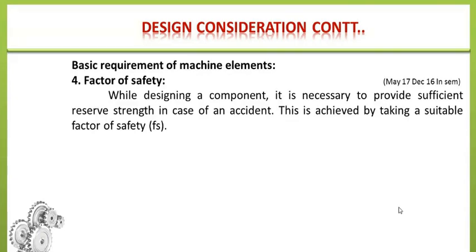So there are two particular points you have to understand. First, the amount of stress generated in the component during working condition, and second, the strength of the material that you select. Now, it is not always possible for the designer to predict all the forces acting on that component. Some forces, because of the very complicated shape of the component, may be neglected by the designer, or because of manufacturing inaccuracy and so on, some forces are neglected.